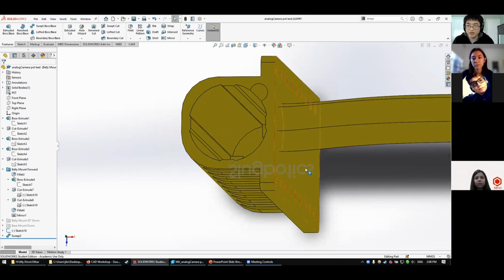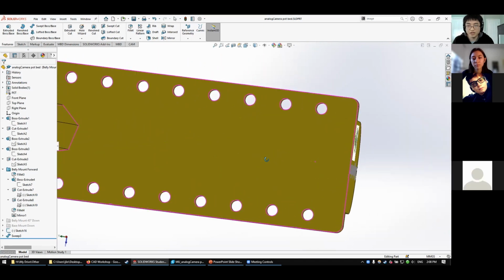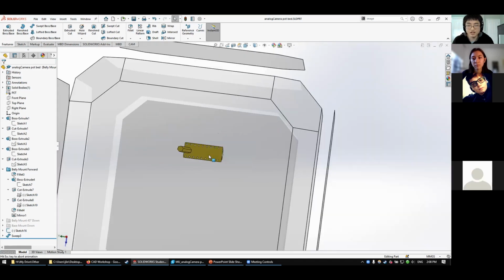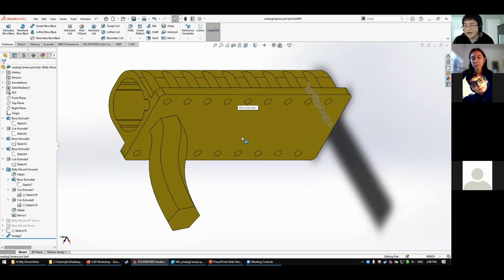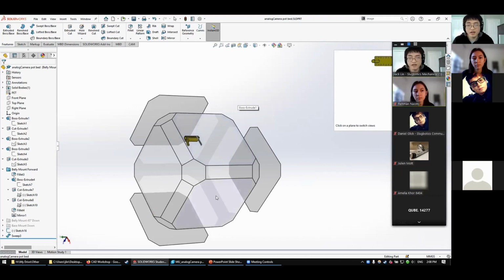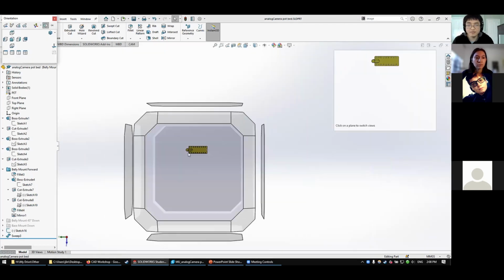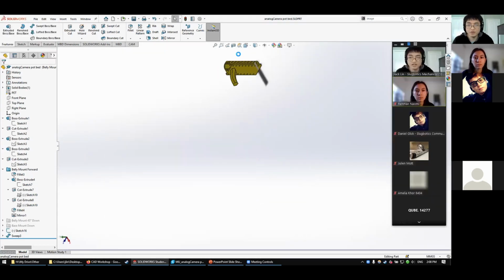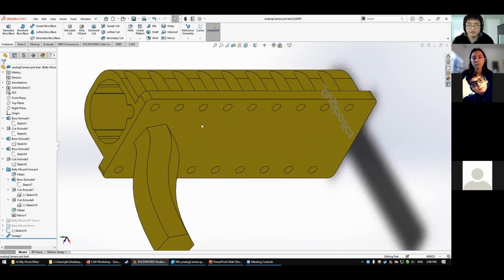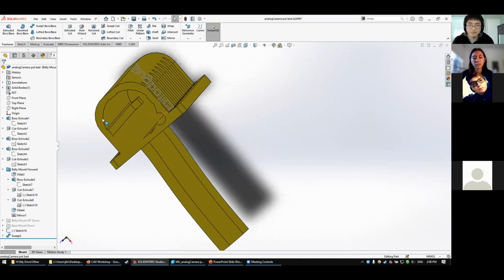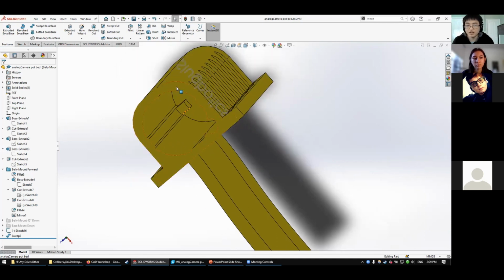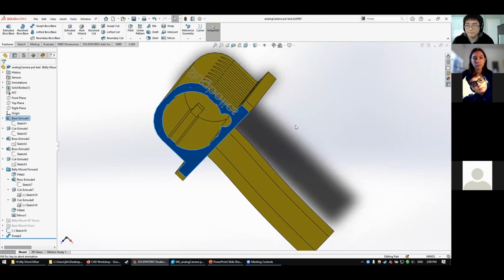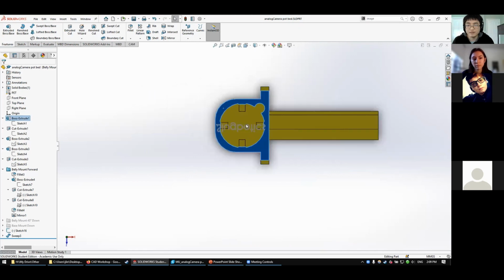If you want to look at something real quick, but don't want to maneuver the camera fully, or if the thing does not align flat against one of the quick views. And the keyboard shortcut I'm doing right here is pressing spacebar to open the quick view. Lets me reorient the camera to one of the presets very quickly. But if the surface you want to look at is not one of those, then you can just right click on something, normal to. That'll let you maneuver the camera very easily.